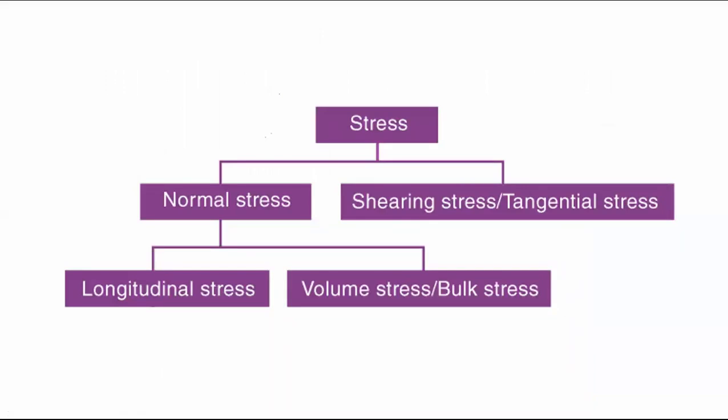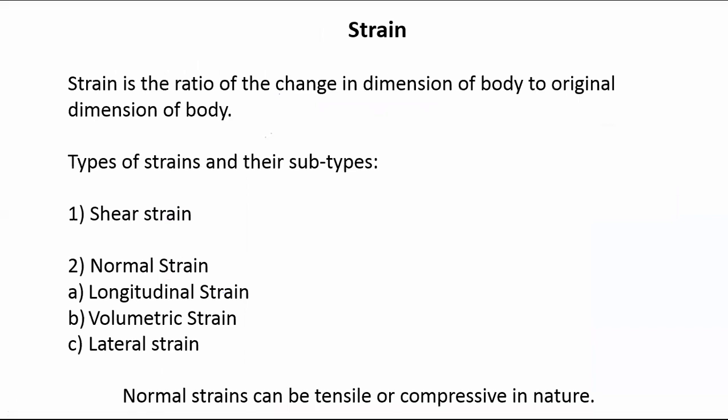Don't confuse between stress and strain; both will be generated. We are talking here about transverse, or it is also called lateral strain. And a volumetric change will create a volumetric strain. As soon as there is a change in volume, that change in volume divided by the original volume gives us the volumetric strain.